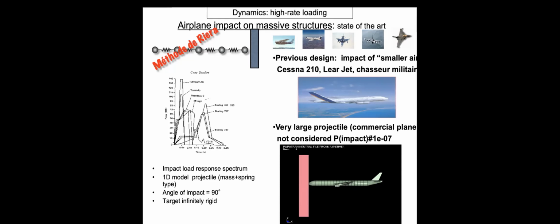And then basically this way you only define the loading that goes into a structure. Then you really have to take a serious model of your structure to be able to see if the structure is going to be penetrated, which is what you're trying to prevent, or if it will just be damaged without any penetration. So you really have the protection role of your structure ensured.